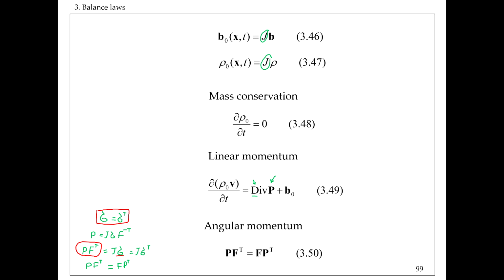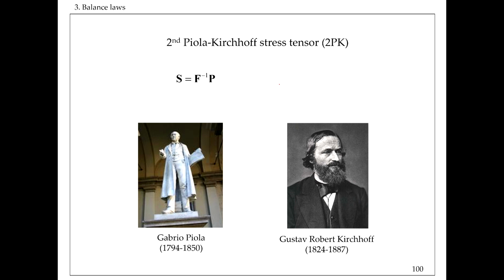Now, all right, so one may wonder, why did we have the first Piola, and doesn't that mean that we have a second or third? Well, yes, the answer is partially yes. We can introduce a second Piola-Kirchhoff stress tensor. One motivation is that we can make it symmetric by simply multiplying the first by the inverse F from the left, right? And so then we can connect that to the second Piola-Kirchhoff stress tensor.